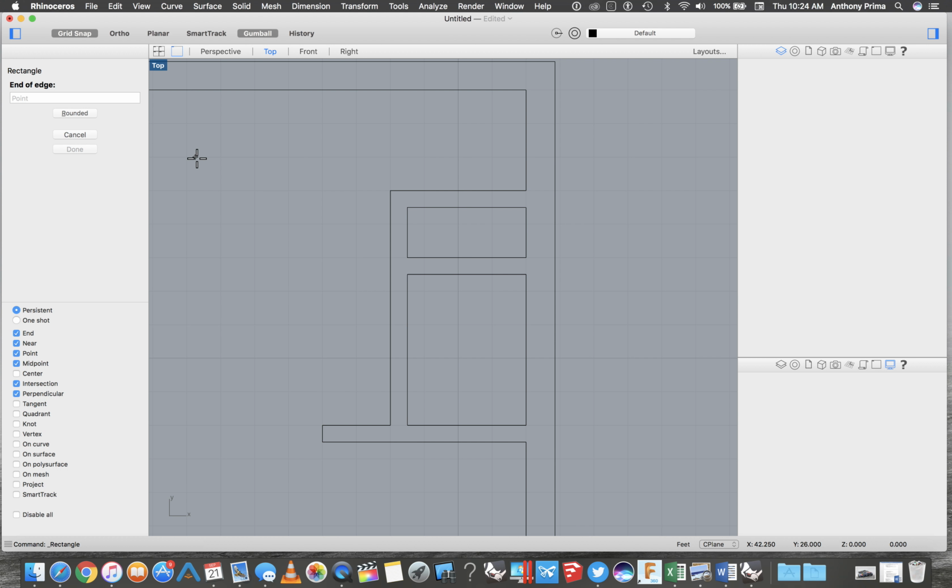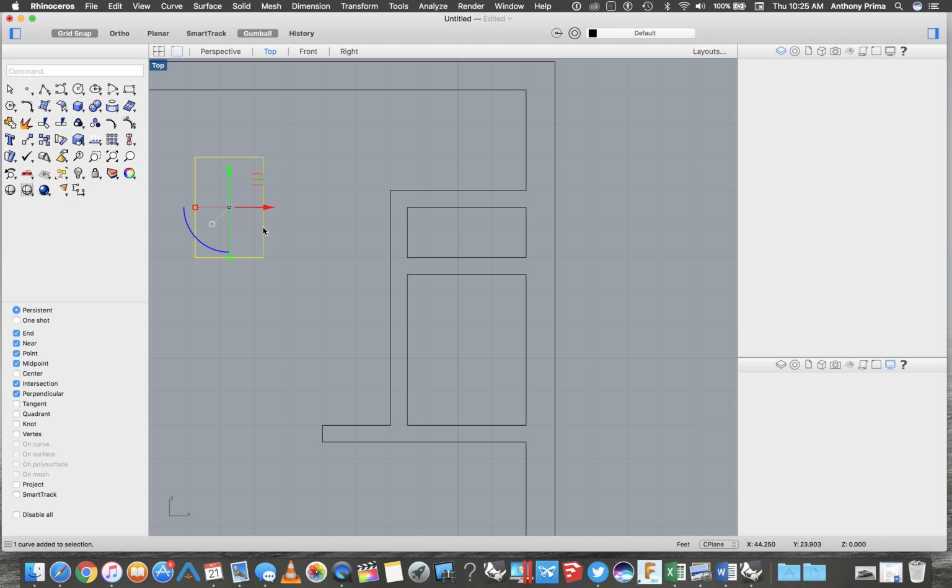Basically what the 3-point tool allows you to do is, if you're drawing a line and you place the first point, I can give a dimension. Say I want 2 feet, and it will automatically snap that to what 2 feet is. If you hold shift down, that'll automatically place it on a horizontal or vertical line. And then you can do the height of it as well. Say I want 3 feet. It'll automatically snap it to 3 feet. So I'm just going to go ahead and delete that, and I'm going to place it on here. Oops.